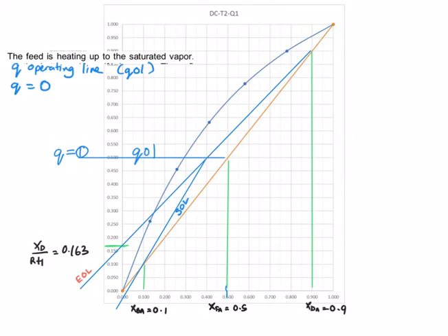Starting from your distillate, you're going to draw the stages. So starting from here, you just draw the stages. Okay, so the boundaries is this one. This is where you have your EOL, and then you have to go through here. Alright, because when you draw the stages, it must be outside of the EOL and SOL.